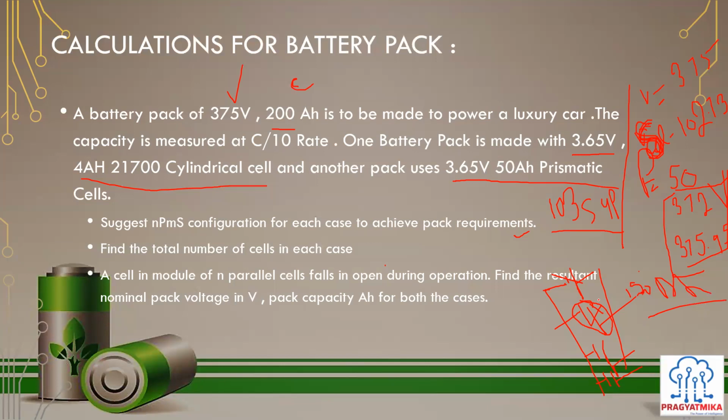But if the same case happens in a series connection, what will happen? Like now we are making a series of 103 cells. One cell gets open. What would happen? I think the whole series will open. Whatever, that depends on the position of the cell. No, the connection will get open. Total connection exactly gets open. So the total pack voltage, you will not be able to measure, right, due to the open connection. So there individual monitoring is required.